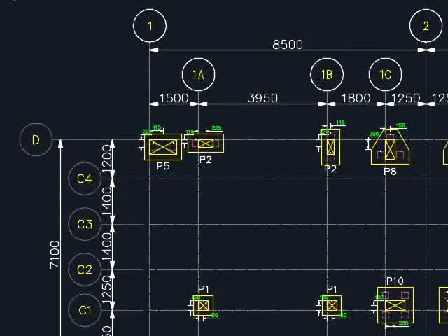But you know that you need to design the foundations, be it pad footings or pile caps, to be at the center of gravity of the column, more specifically the center of the loads. If there is only one column per foundation, automatically the center of gravity of the column will be the center of the load. This will need to be in line with the center of gravity of the foundation.